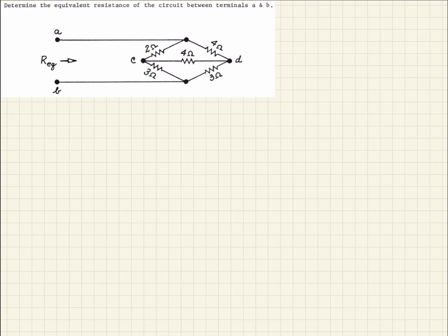So with Delta-Wye transformation, if we have resistors connected in such a manner here, and we'll call this terminal 1, 2, and 3, then this will be lowercase r1, lowercase r2, lowercase r3. We can change the configuration to look like this. Again, where this is 1, 2, and 3. But this time we'll have a capital R1, a capital R2, and a capital R3. And our capital R's values can be written in terms of our lowercase r values.